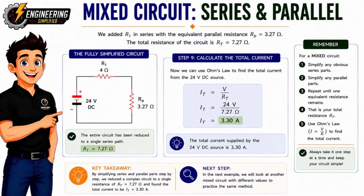The formula is current equals voltage divided by resistance, or I sub T equals V divided by R sub T. Now substitute the values. The voltage is 24 volts and the total resistance is 7.27 ohms. So, I sub T equals 24 divided by 7.27. This gives us a total current of approximately 3.30 amps. And that's the current flowing from the power supply into the circuit.